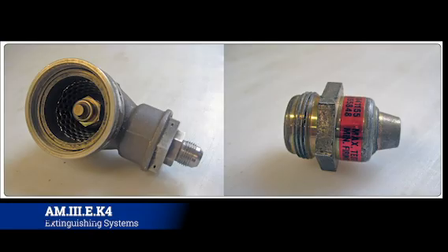they have created what we call a squib, which is an explosive cartridge that mounts to the fire bottle. Whenever that squib has an electrical circuit tied to it and it goes to ground, the charge in it simply explodes. When it explodes, it blows out what's called a discharge disc. That discharge disc is what's holding back all of that fire suppression agent inside of the bottle.